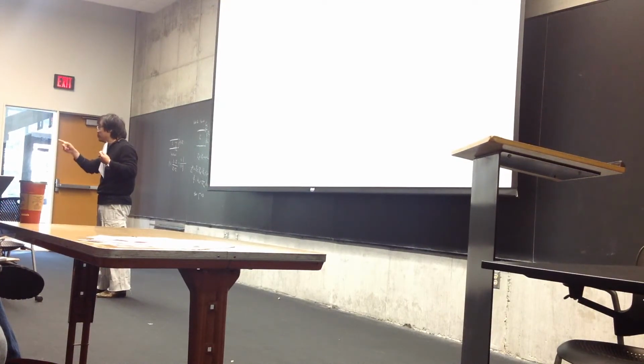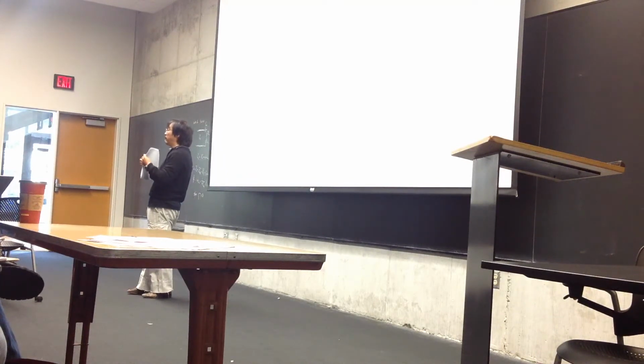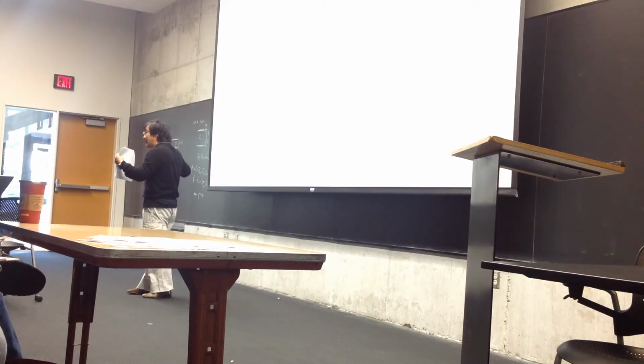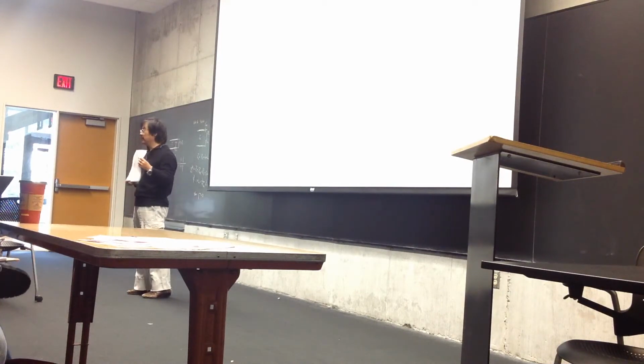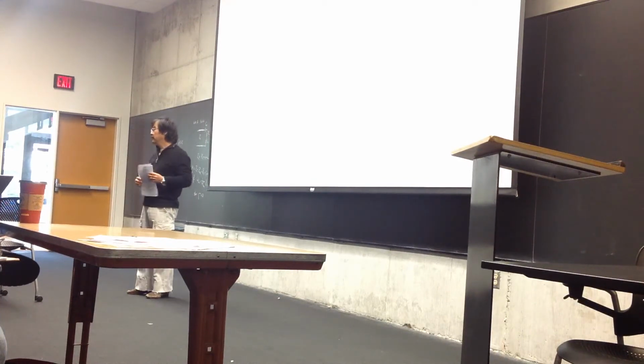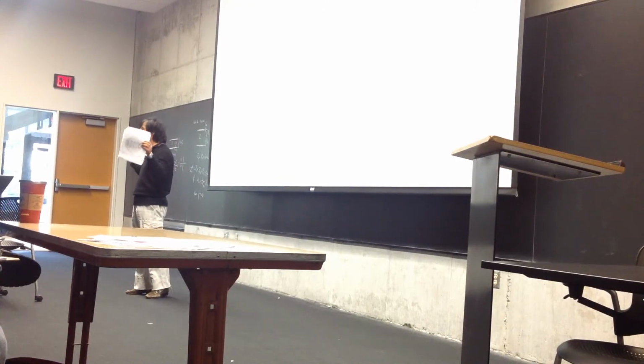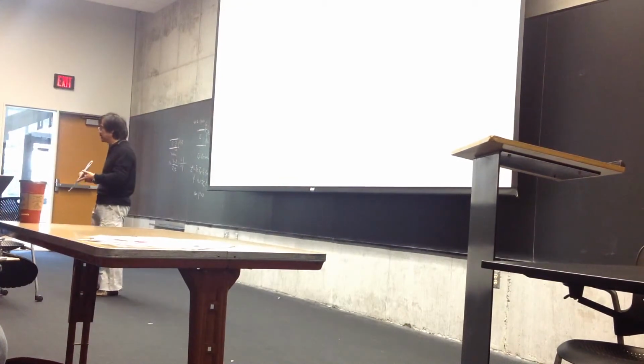So there are 2 solutions. You choose the one which is cheaper. You can understand what I mean by cheaper? But they both work. Okay. So you want to choose the one which is cheaper. You are going to see the location you choose will also affect how much wire you need to provide in order to match it, and you want to choose the one which costs you less. Theoretically, you can have an infinite number. But also the transmission line may actually only have a finite length. So that's another consideration.